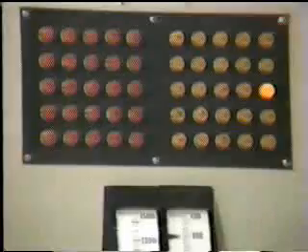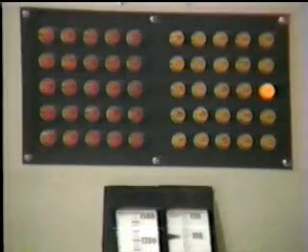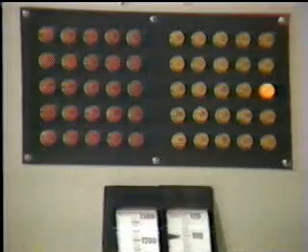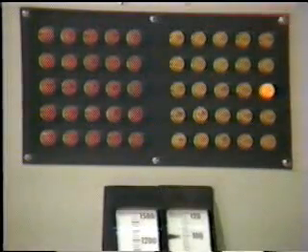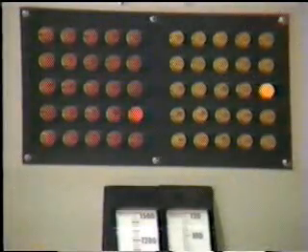The gas monitor Z299 receives an input signal from sensing device G399 located in the package enclosure. If the amount of gas inside the enclosure reaches 20% of the lower explosive limit, Z299 will activate warning light number 48 and the horn. If the gas continues to increase to 60% of lower explosive limit, the monitor will transfer contacts, causing malfunction light number 24 to illuminate and the start-run relays to drop out.